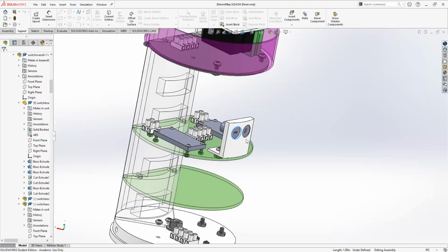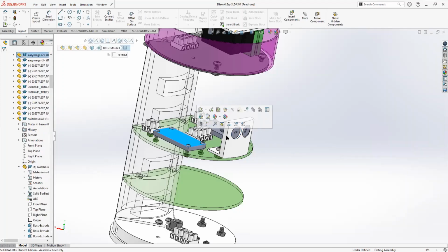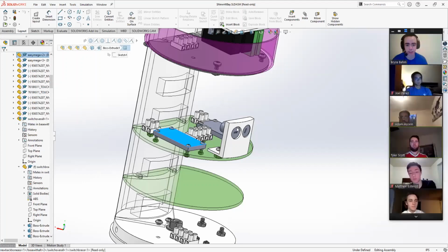Okay, so these switches on the side, you can turn with a screw, and using that screw you're able to turn the altimeters on and off. That's useful because altimeters work on pressure. If you don't do that and you just put them in, they will activate and say, oh, I'm flying now, before you actually start your flight. You want to be able to turn them on as soon as you get to the pad, because you don't want to be messing with electronics on the ground, because the altimeters also control the ejection charges. If you turn on your altimeters prematurely and they detect a flight, and then decide flight's over, they'll blow up, and that could really hurt someone. So you have to be able to activate them on the pad. That's why you have these switches here.